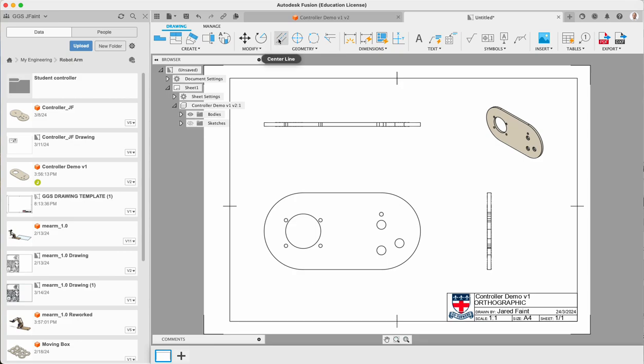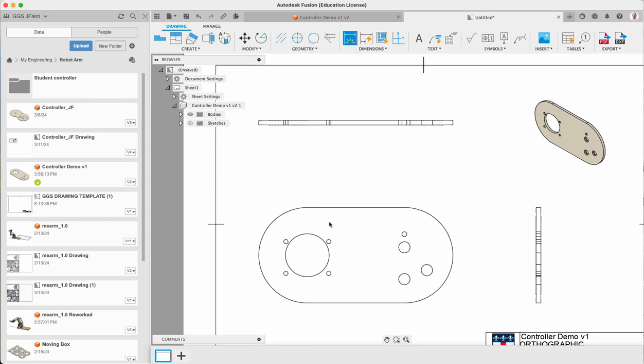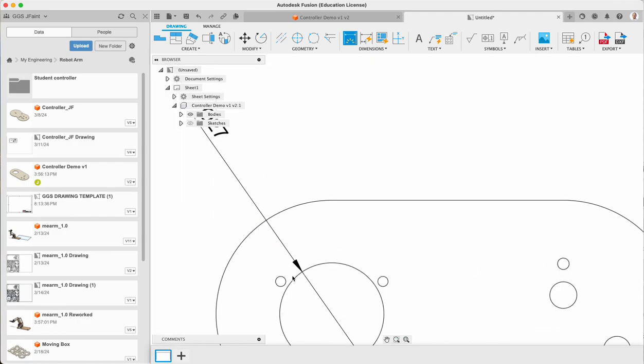So I can add center lines. If I need to, I can add in the center lines on the other images for my circles. Now in this case, it's probably not super helpful, but if I wanted to, I can then grab my dimensions. I'm going to then, the shortcut is D, just like it is on the drawing pane. Make sure that we draw those over there.